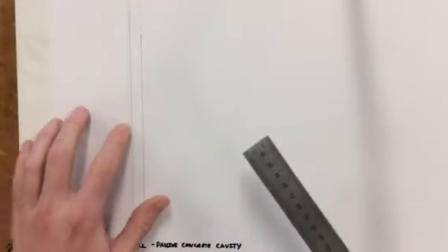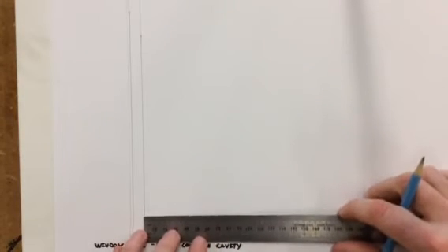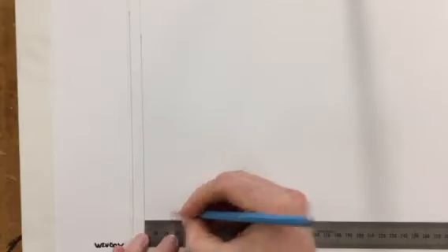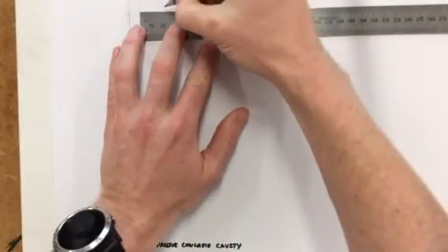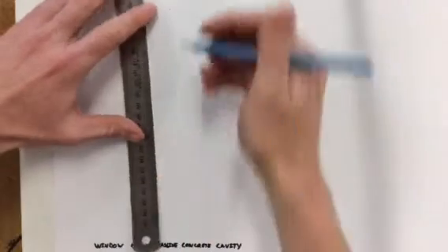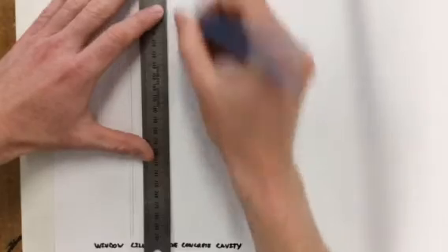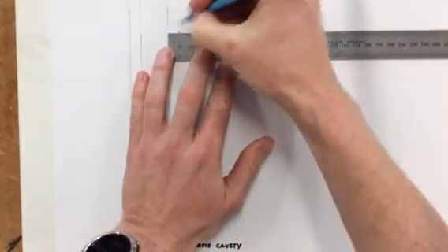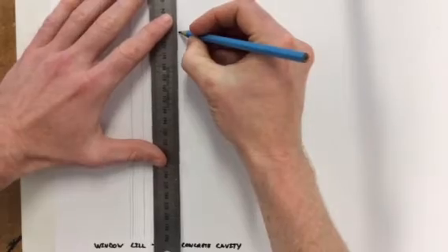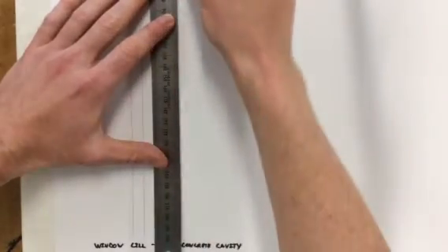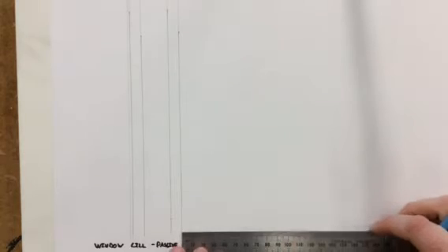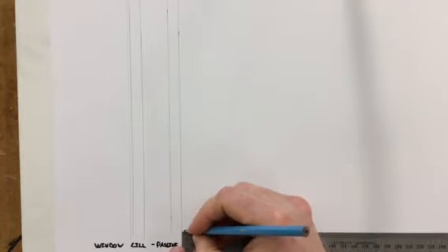Now I have external render and a row of blocks. Then I'm going to look at putting in my insulation. It's a passive house, so there's 250mm of insulation between the inner leaf and the outer leaf. Again, measuring twice. Insulation's going there. Then I want my inner leaf, the internal row of blocks, and then my internal plaster would be around 12 to 15mm.